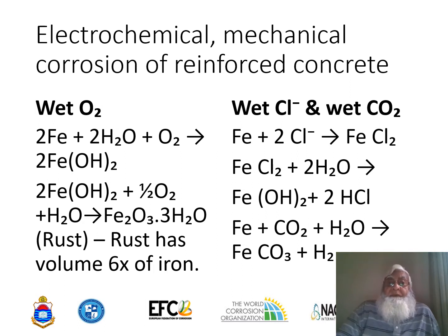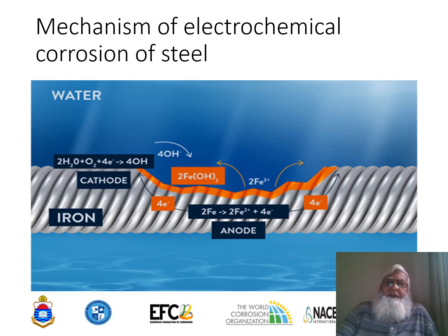The second reaction which is possible for the corrosion of the reinforcement involves the chlorides and wet carbon dioxide. The iron of the reinforcement reacts with the chlorides coming from the atmosphere or from the water mix in the concrete or any other source, forming the iron chloride plus water, which ultimately goes into the